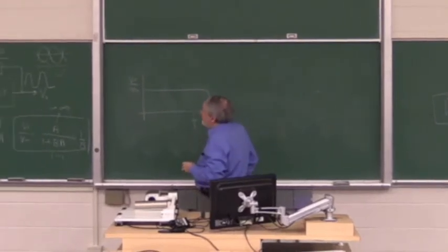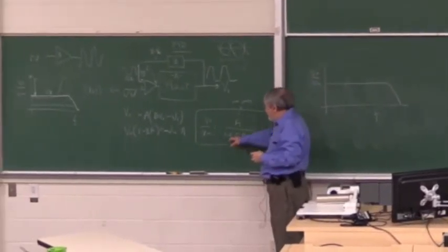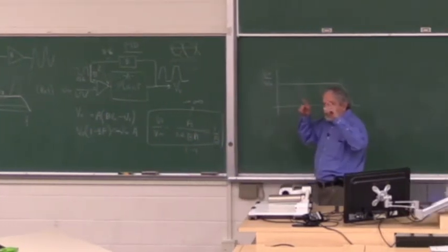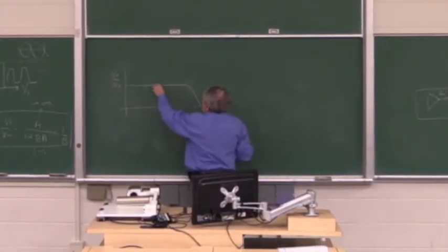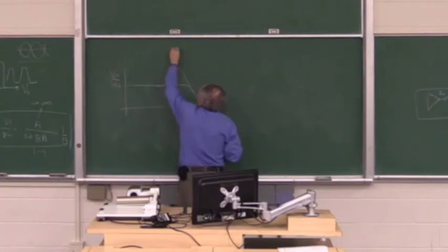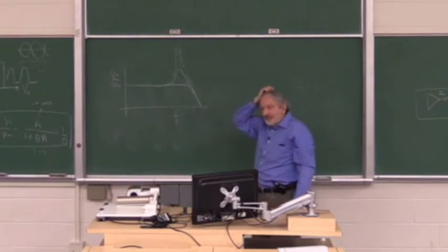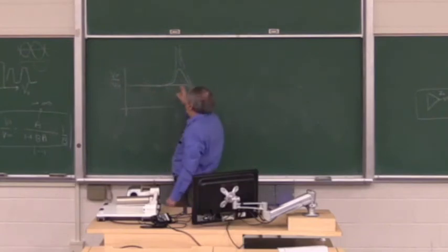Now, if the phase shift starts building up, this starts reversing polarity and cancelling the 1, and then it will start what's called peaking. The amplitude will start growing. And it always happens at this end. In other words, when it starts becoming unstable, it looks like this. And then if the phase shift goes even higher, then it starts oscillating. It goes to infinity. Now, can somebody explain why the problem is always occurring here at the end before it rolls off? Like it will never oscillate here in the middle. It will always oscillate here.